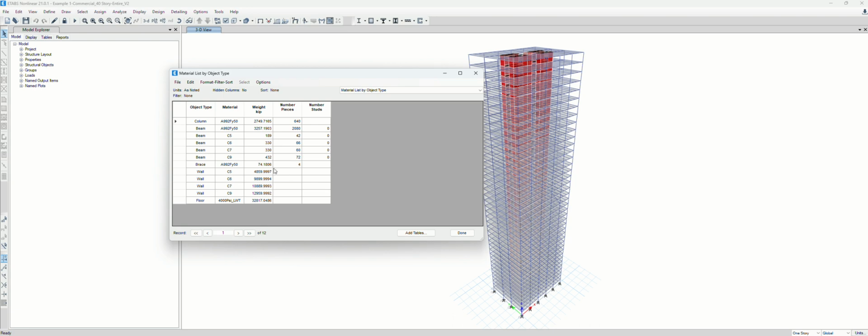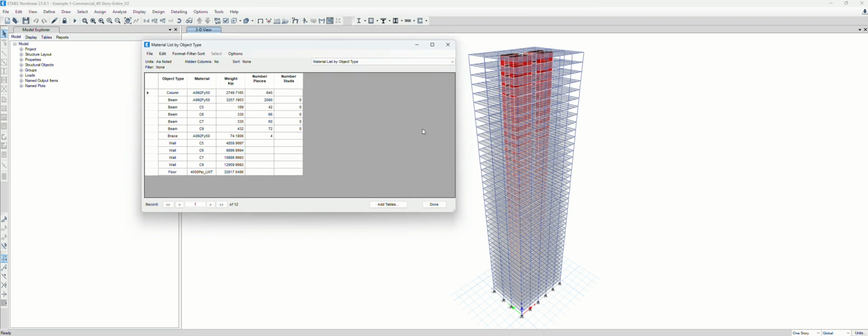The total weight divided by your concrete density gives us the total equivalent concrete volume. Then divide by 27, since we usually use cubic yards. So you need to summarize all your material takeoff, steel and concrete. For steel, you should sum them up as tons, and for the concrete you need to calculate back to cubic yards. This is very basic, so I want everybody to really understand and complete it.